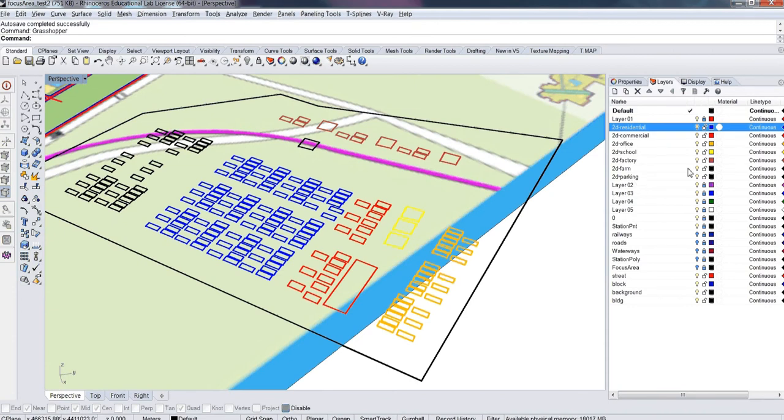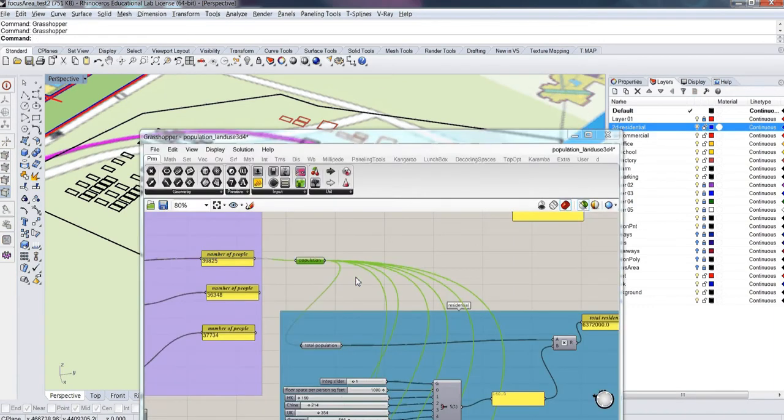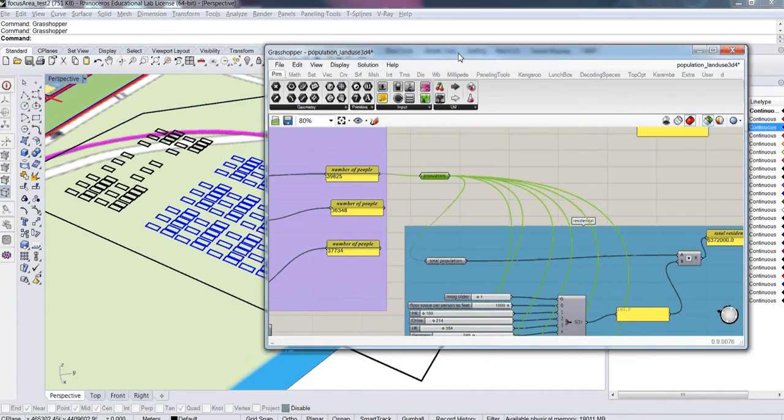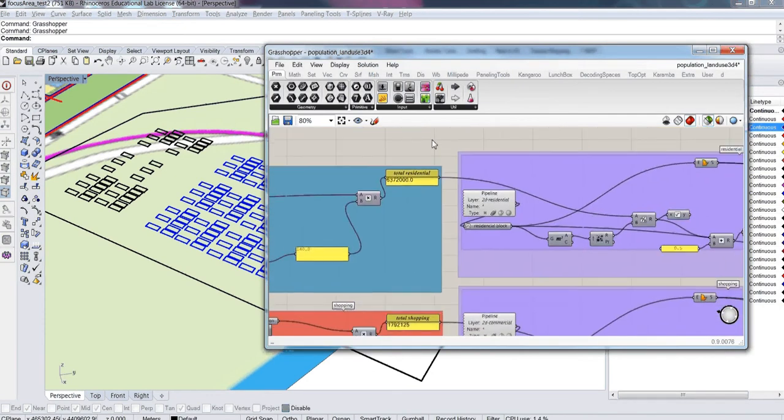So my goal, in order to transfer this file to Scenario 360, is to generate a 3-dimension model first. Second, I'm going to move this 2D footprint along the z-axis to reflect the height, the elevation. So Scenario 360 can read the elevation data from this footprint. That's some new components I added in Grasshopper. Let me explain them one by one.